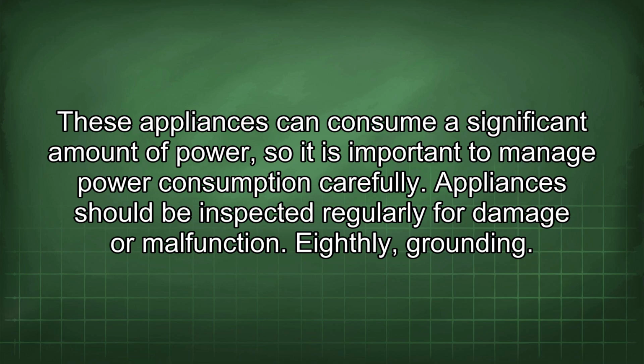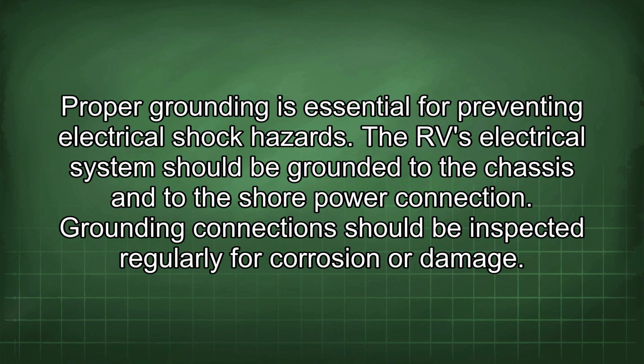Eighthly, grounding. Proper grounding is essential for preventing electrical shock hazards. The RV electrical system should be grounded to the chassis and to the shore power connection. Grounding connections should be inspected regularly for corrosion or damage.